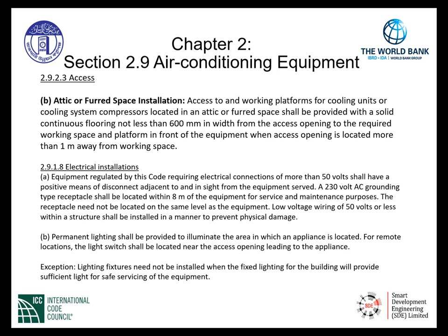2.9.1.8, item A, equipment regulated by this code requiring electrical connections of more than 50 volts shall have a positive means of disconnect adjacent to and in sight from the equipment served. This is very important that we have an electrical disconnecting means to the equipment requiring service.